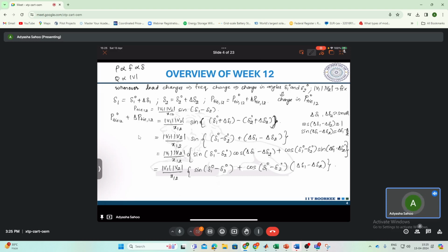So if I multiply this V1 V2 by X12, this first term will be nothing but your P tie 12 naught, plus this additional term will come, that is V1 V2 by X12 cos of delta 1 naught minus delta 2 naught into del delta 1 minus del delta 2.